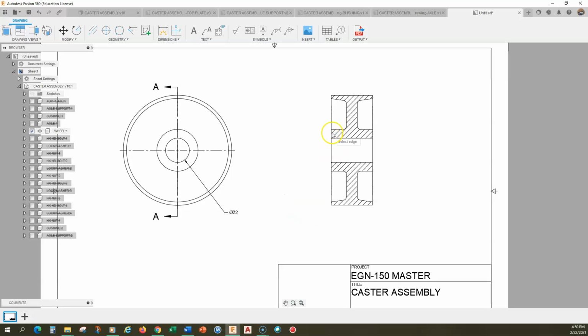So we have a cylinder now, the outer diameter here. And generally speaking, it's better to dimension between views. It makes looking at the views a little bit easier to understand. We'll dimension this as well. The main difficulty on this drawing is how to handle this angle right here, right? Fillets and rounds, we're just going to have a note, so I'm not even going to worry about dimensioning that.